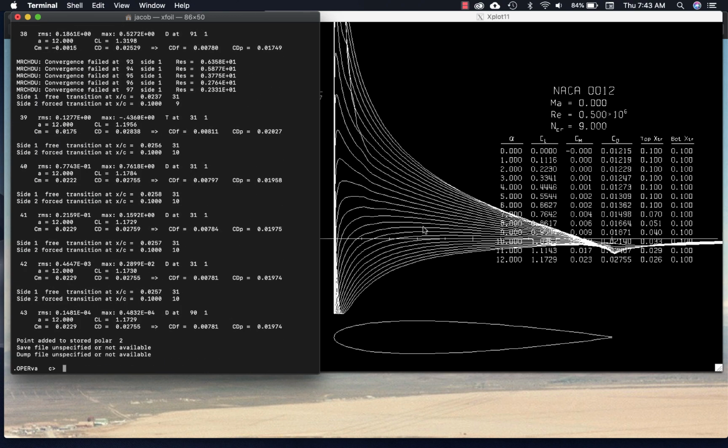You'll notice in this case, oh, look, my laminar separation bubbles have now disappeared. I don't see them in this plot like I saw before. They're all located up here because I'm actually forcing the flow to transition from laminar to turbulent flow at this particular location. In most cases, for these angles of attack that I ran, my flow is still laminar here.